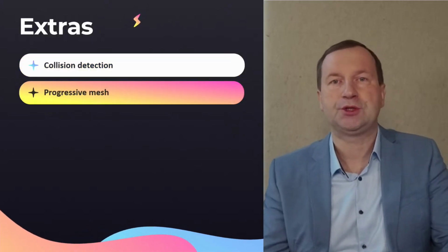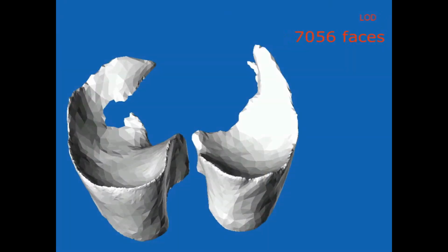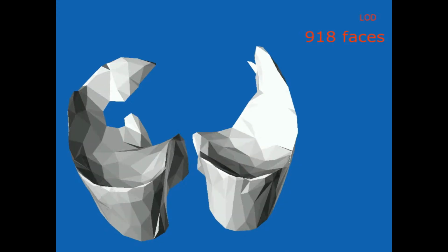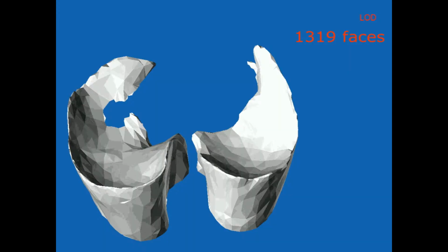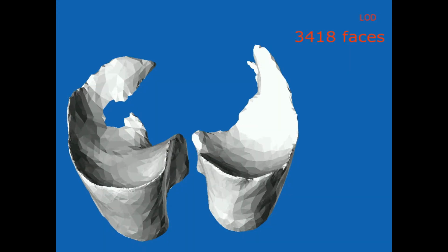Finally, we want to close this overview with a feature called progressive mesh. There's a special geometry primitive in the Visualize API that can be created based on the input shell object, or in other words, a triangulated body. This object can generate its own representation at varying levels of detail and can dynamically switch its level of detail in real time.